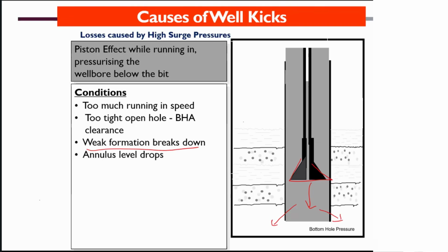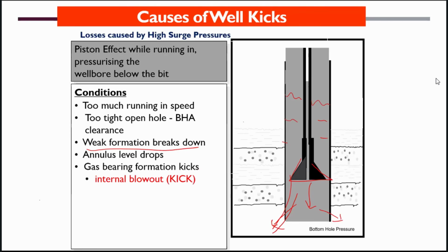If the formation breaks down, mud will be lost, then your level also will drop. Mud level will also drop in the well. If mud level drops, hydrostatic head will drop and gases from the formation can enter your wellbore. So this is due to surging.